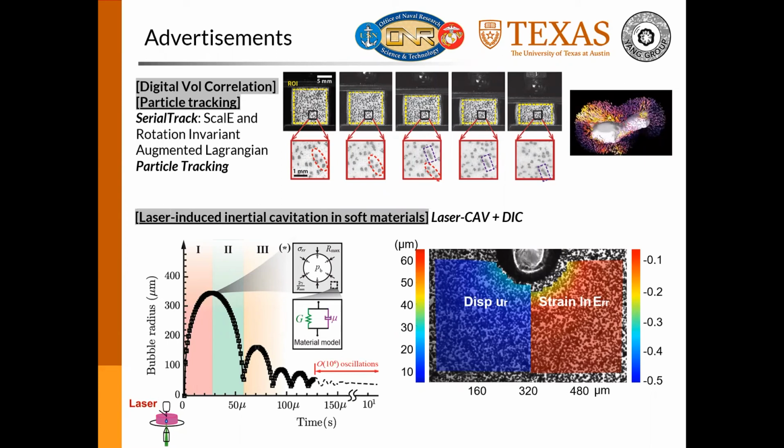Oh, that's a good question. Your question is actually related to how we paint those speckle patterns. For 2D DIC and also stereo DIC, you only track the surface of the specimen, so I don't think transparency is a problem there, because you only track the top, outermost surface. Also, I can send you a very nice review paper from 2014 or 2016 that introduces how to paint a pattern for hard tissue and soft tissues.